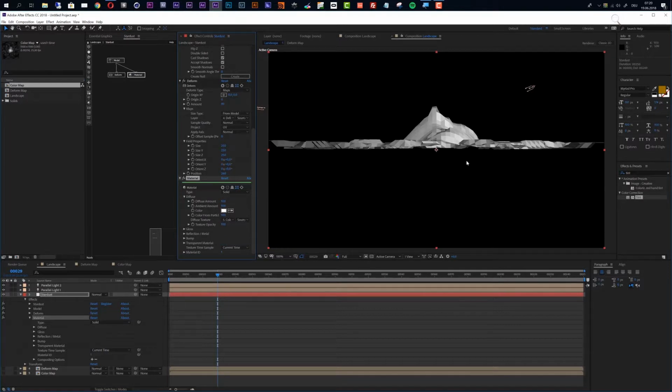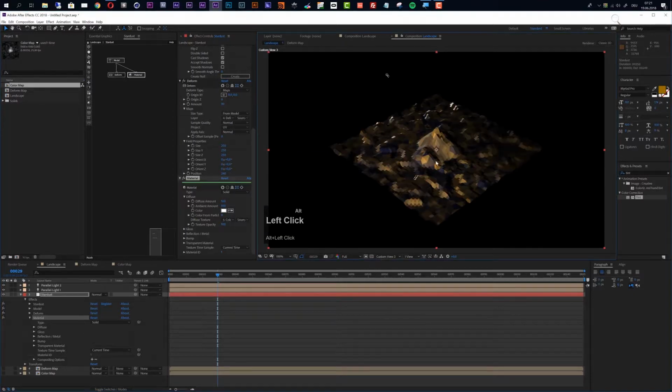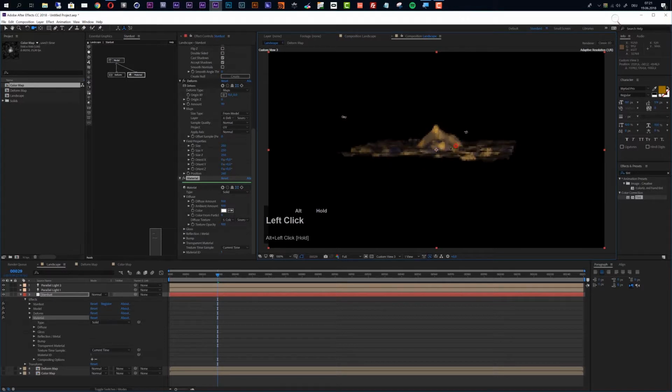And you see that nothing is happening, and this is because the color from particle value is set to 100. And if you reduce this to 0, then our texture will be colorized. If this is set to 100, then the material is looking for a particle node and the color of this particle node, but we have no particle node, so we have to reduce the color from particle to 0, so that our diffuse texture is working. And now you see that we have a nice coloring of our landscape.